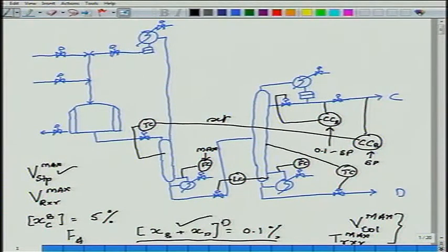Yeah. Then the problem was, how do I control? The rest is straightforward, you know, the inventory control system. I have taken care of this one, this is going to become maximum. So, this will be my throughput manipulator, this is what we discussed last time. This is the last constraint to become active. So, I will use this as TPM. If I want to increase the throughput, I am going to adjust this.